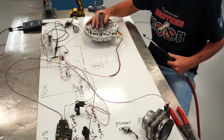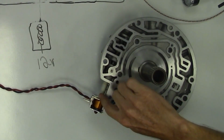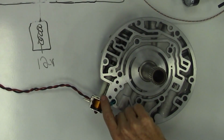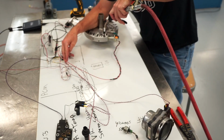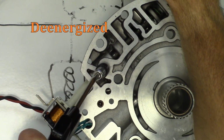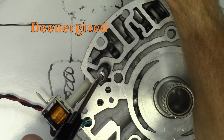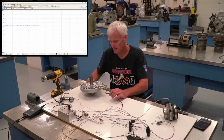Now the way that this ends up operating in the transmission is fluid comes in through this hole, and it's going to leak out through the snout that we've got. And also all that fluid pressure is going to come out when the solenoid's off right through the snout. Then when we energize the solenoid, it pushes a check ball and seals it off. And then pressure builds up on the back side and it shuttles this valve, when I provide power to that transistor and energize the solenoid. So that's basically how an on-off solenoid operates.